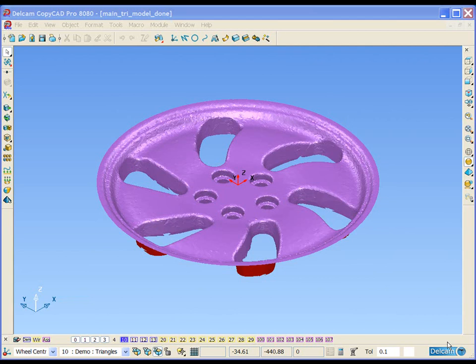During this stage, we shall be using CAD-based reverse engineering techniques to generate a model of our wheel from the existing scan data. We will be showing sectioning, the creation and editing of 2D wireframe, surface and solid creation and editing, and also error analysis.